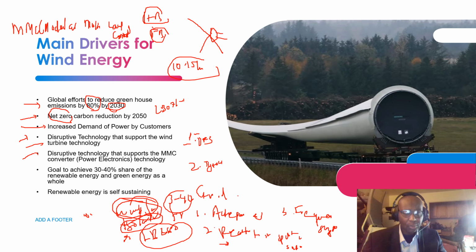and voltage to 0. So when you're utilizing the full-bridge converter technology, you don't need a DC circuit breaker in your DC transmission system. On the other hand, if you utilize the half-bridge submodule as your MMC converter, then you need a DC circuit breaker in your DC transmission system. You need a DC circuit breaker on each end, because the half-bridge submodule does not have that blocking capability for a DC fault current and the ability to control the DC fault current to 0.